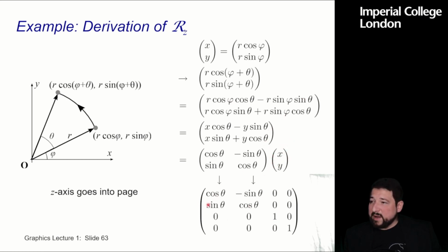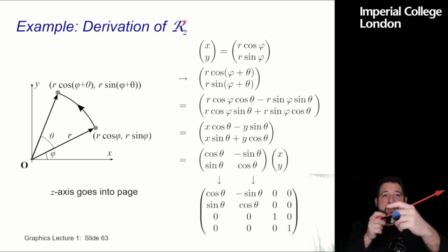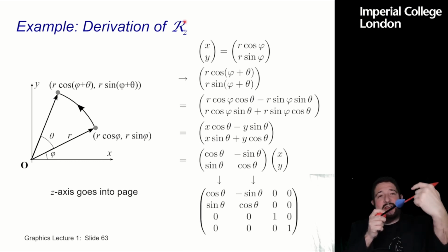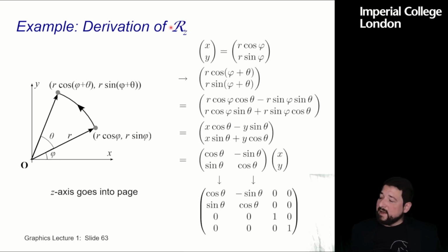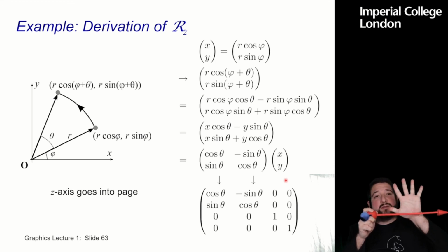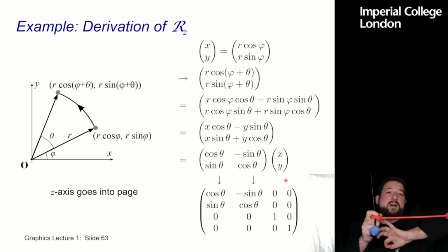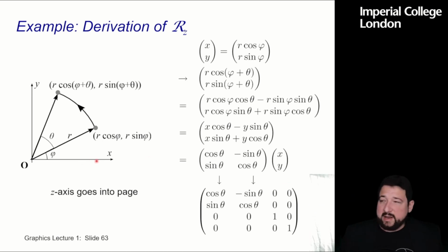So just for x and y, and this component is x and y if I want to rotate around z. So what this does here is building me the rotation matrix R z. So I want to rotate around z, and then I end up with something that gives me a rotation matrix relative for x and y. Of course, because I stay within that plane, z does not change. I only transform every value that lives in that plane around a certain angle here.